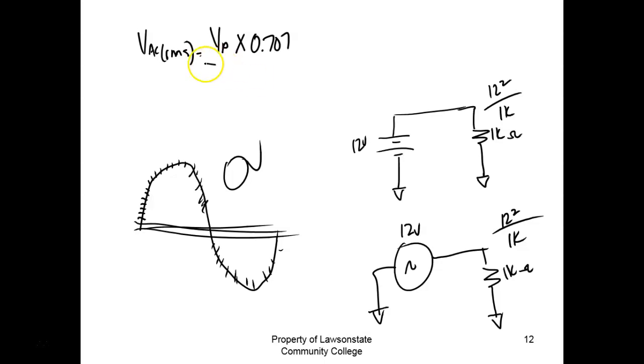Now, this is the way meters have worked for years. But now, when they came up with this thing called a microprocessor, it means that sucker can do math. So we have meters that actually do true RMS. If you took this meter here and this meter that costs twice as much, and all you do is electrical work, and all you deal with is sine wave, you wasted a ton of money on your true RMS meter. These two meters are going to measure basically the same. The only time you need a true RMS meter is if you deal with AC waveforms that are non-sinusoidal.